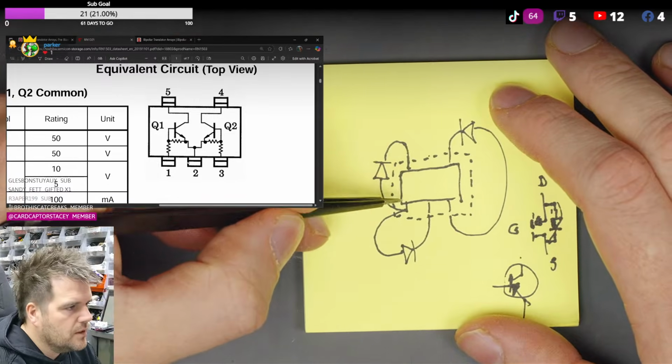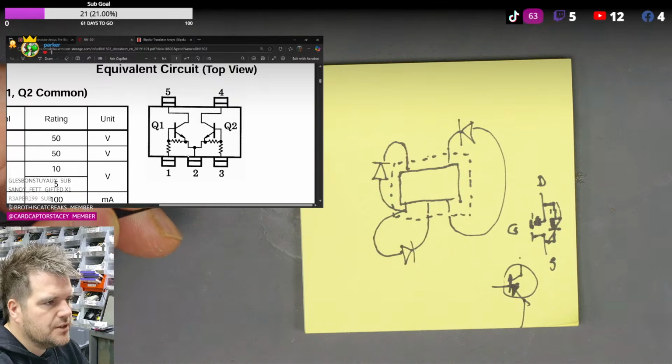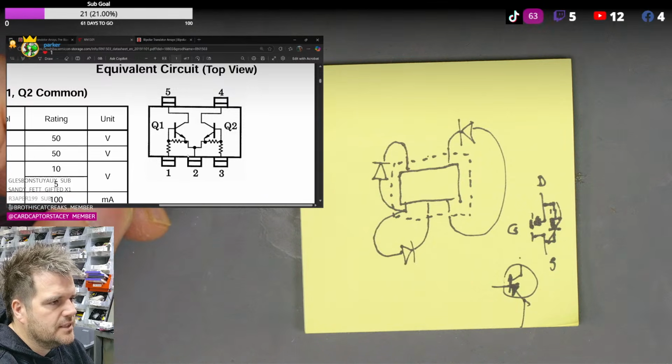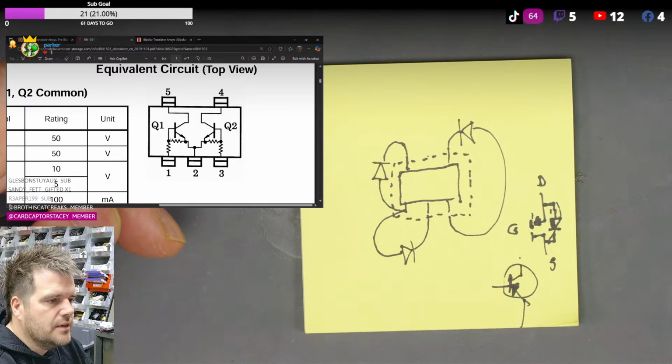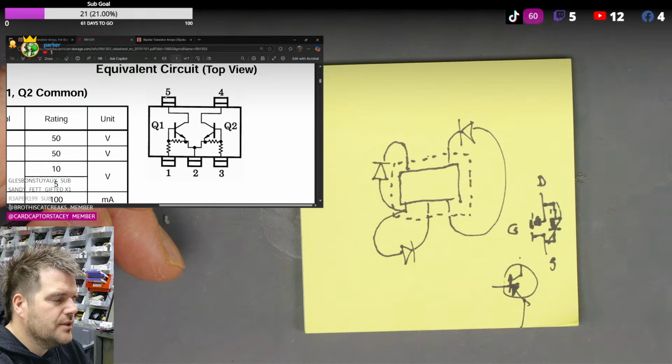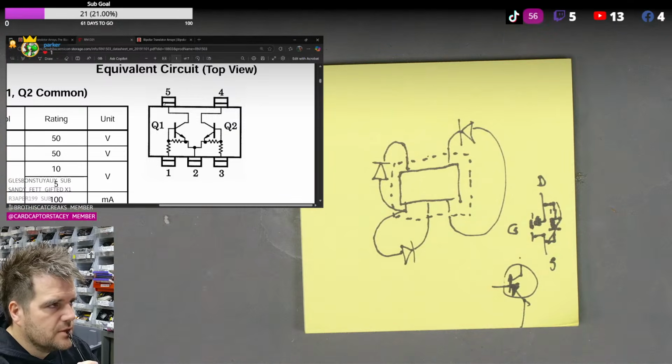If we have now, you can see a transistor on, you'll have a diode that reads from pin 1 over to pin 2 potentially on that. But on here, this is almost an epitaxial setup. But obviously, all it's doing is pre-biasing the base where the resistor is pulling up. So we'd have resistance between pin 1 and 2 if this was the case. We also shouldn't have a diode reading between pin 5 and 1 because that's the base and the other pin, so it's not going to be that.